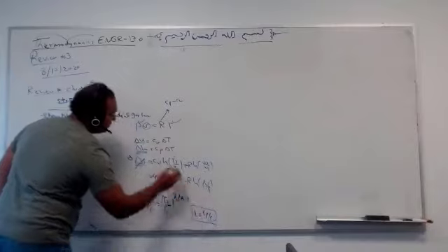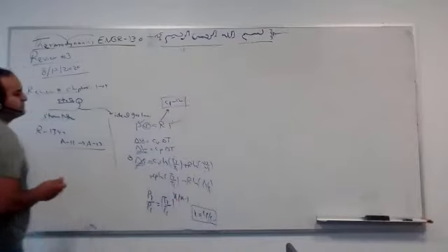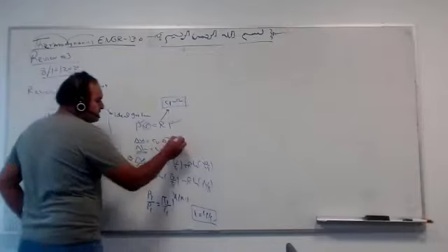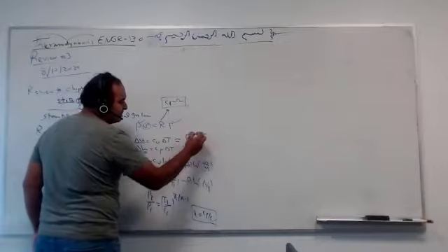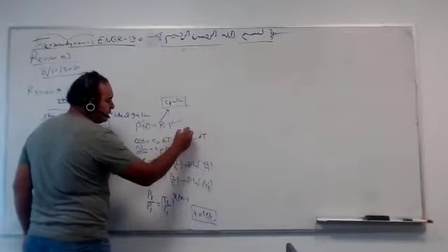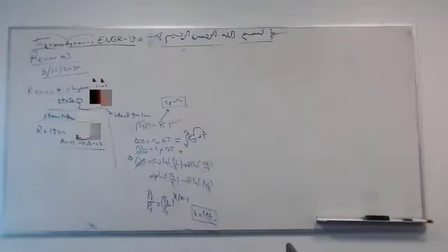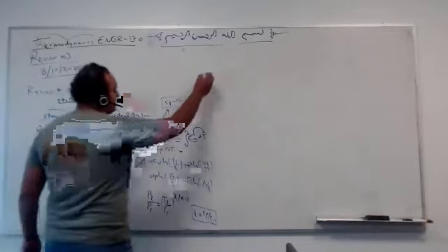So K is the specific heat ratio, and this is the specific heat difference, the gas constant. And we have tables for them. Table A2a, room temperature; A2b, average or distribution; A2c, we have the function. So in reality, this equation was originally the integration of Cv delta T, here from T1 to T2 and so on. Cv is a function of temperature, which is table A2c. That's a quick summary of chapters 1 to 3.